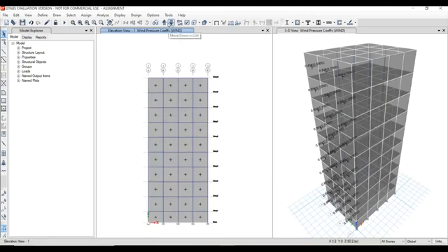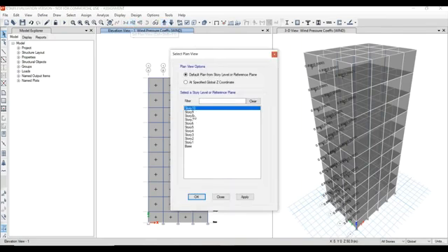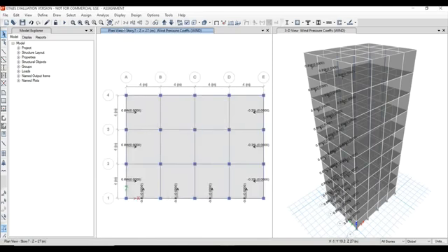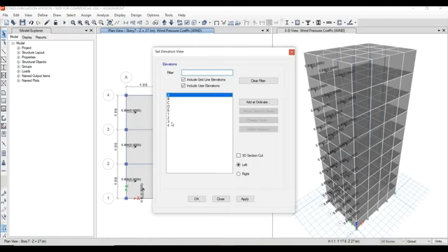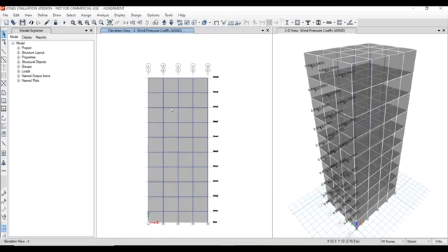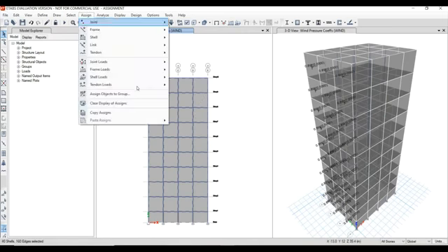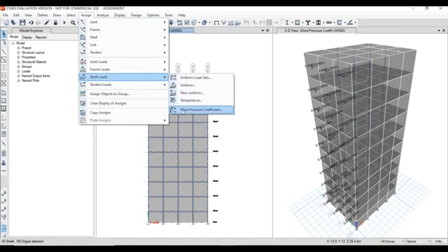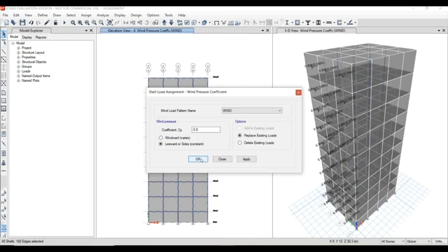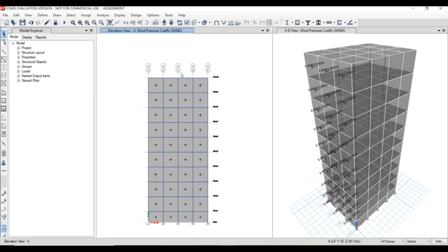And also we need to go to plan view of any story. We need to select section 4. So select elevation 4. Okay. Now select every story shells. Now assign shell loads wind pressure coefficient minus 0.8 leeward. Okay. So every direction is assigned with the wind load.